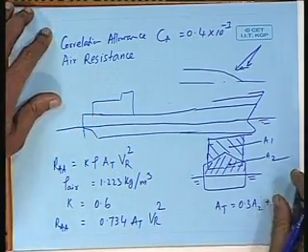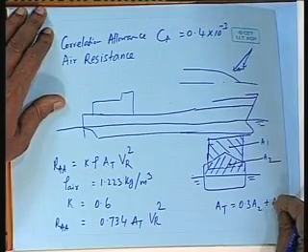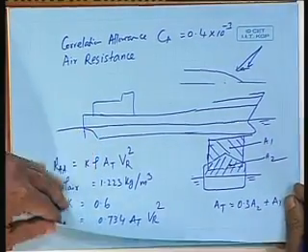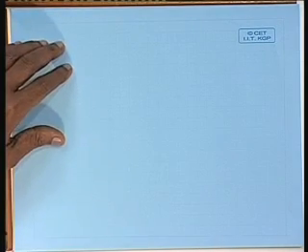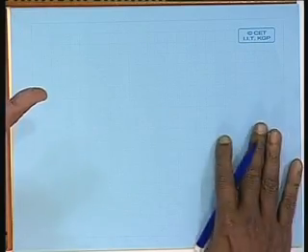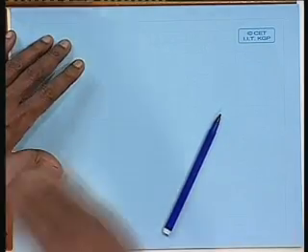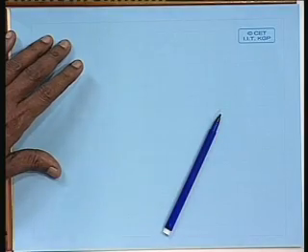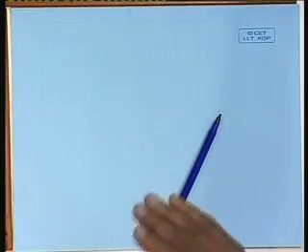Now, there is a very interesting phenomenon in the wind resistance case. If the ship is very tall, if it has got a large windage area on top, then there is a problem, because the wind velocity changes from the water surface to a height. At the water surface, you can imagine there will be friction between wind and water. So, theoretically the wind velocity is 0, and it will very quickly pick up to full speed.